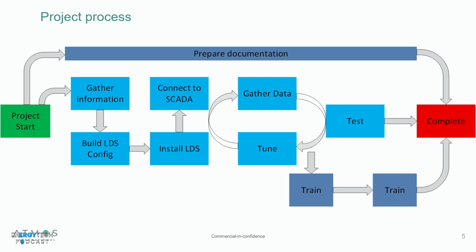Yeah, I think we've probably worked with all the larger ones. Generally, when we're putting this type of product in, we're connecting to what's already there. So the leak detection system itself will be using the existing instrumentation, flow meters, pressure sensors, and then also the control system. So we're very agnostic on control systems. And it's just a case of finding whatever protocol is available, again, existing, and we'll make that connection.